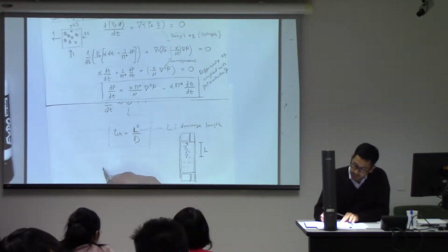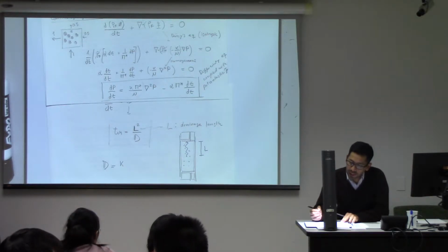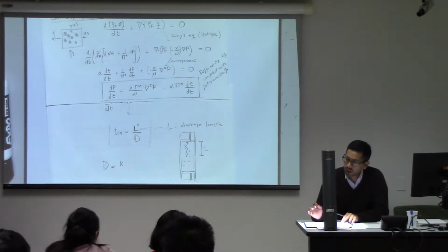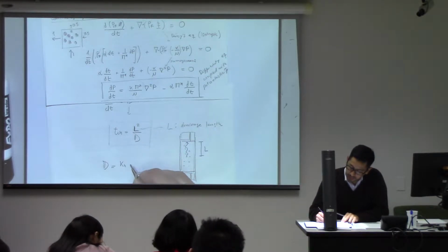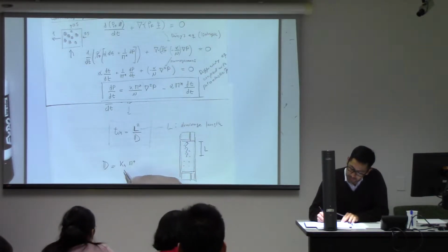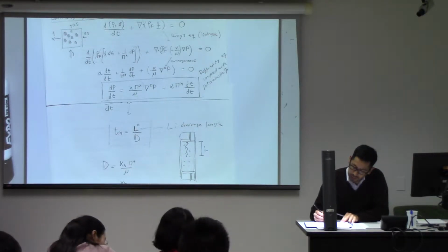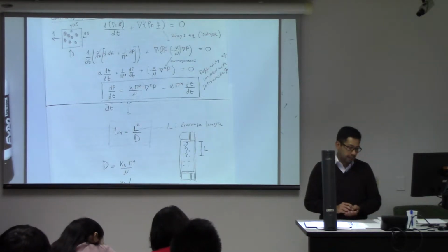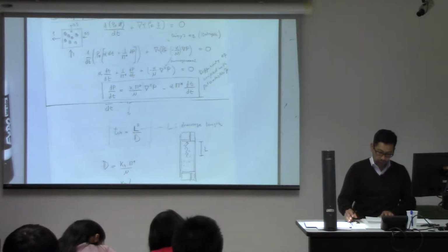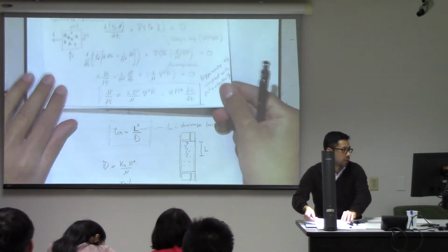In this case, the diffusivity parameter is K, where, in order to make this clear, I'm going to add the H from hydraulic. So it's not the same K as the K from stiffness: K_H times M divided by viscosity. I can calculate that M, and that M, as we know from our equations, is something that we derived somewhere over here.